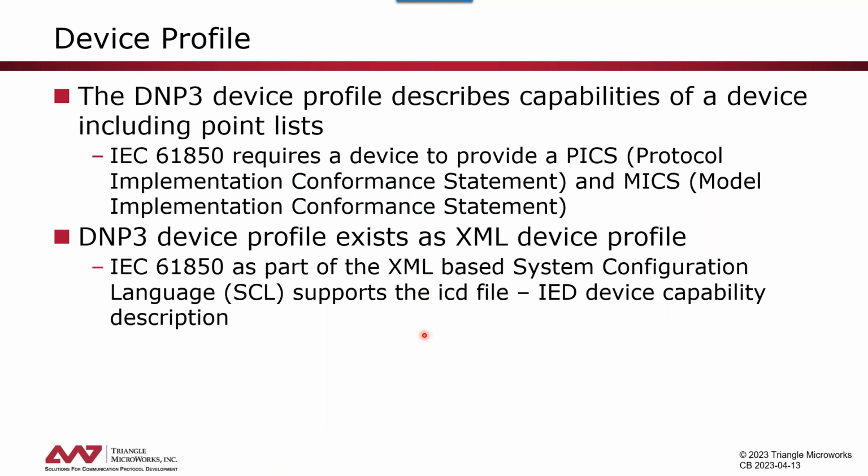Okay, the last point I would like to mention is the device profile, or the corresponding element in 61850. So a DNP3 device supports a device profile which describes capabilities of a device, including a point list. In IEC 61850, in a similar way, we require that the device provides a PICS, protocol implementation conformance statement, and